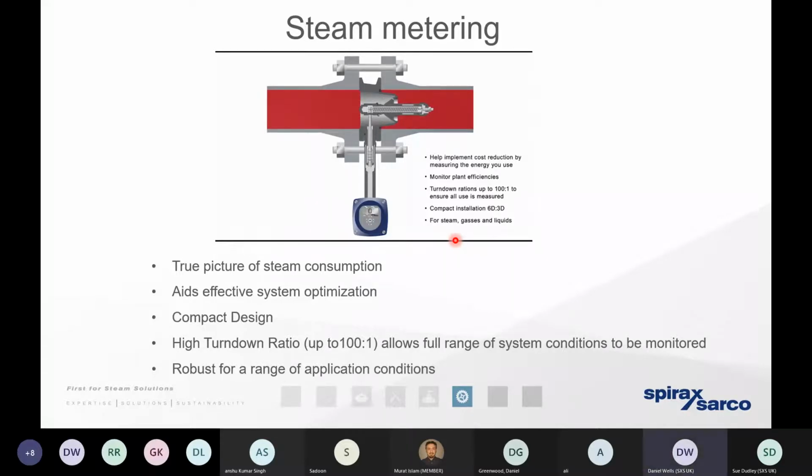And there's another benefit, because if we've got another meter, hundreds, thousands of meters away at the process, well, we can determine if the mass of steam is arriving at the rate that we expect. In other words, understanding if there's any leaking steam traps or leaking valves somewhere around the distribution pipework.